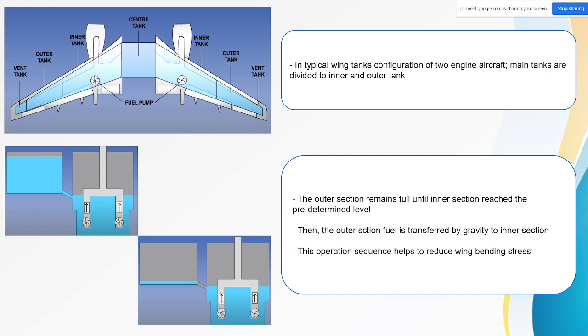For this, because the system is like that, I looked at some systems and they stated that the scavenge pump will drag the fuel from the center tank to tank number one. But I think because tank number one is also used for the APU system, maybe there is some balance in that, because as tank number one is consumed by the APU, it gets replacement from the center tank. Oh, I see. Or maybe there is some imbalance.